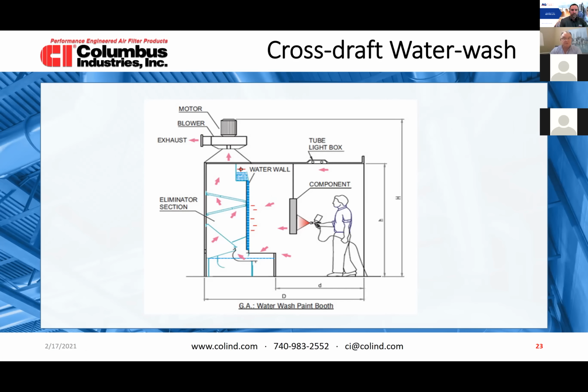So a new water wash is good. As it gets older, there are a lot of opportunities for conversion. It's a lot of opportunities both for us as filter professionals, but also for the end user. Water wash systems traditionally are used for heavy applications. And up to lately, I'd say probably 3, 4, 5 years ago, when we came up with these extended surface filters, there was not a solution that could cover that heavy paint. You had to change the filters every shift, every 2 shifts, and so on, with the flat rolls.